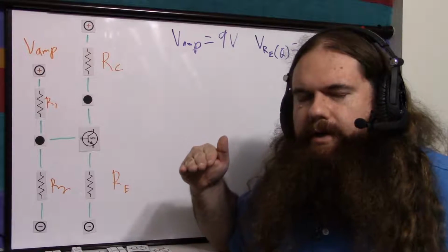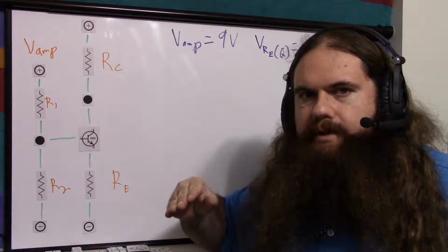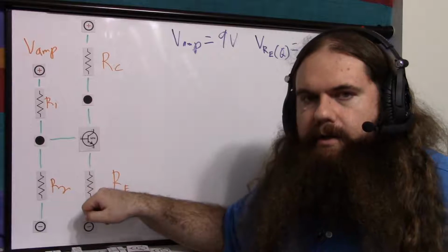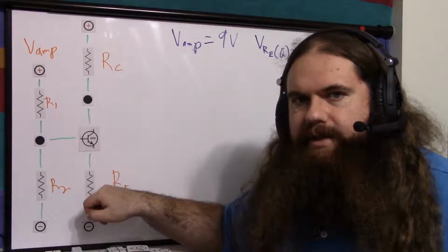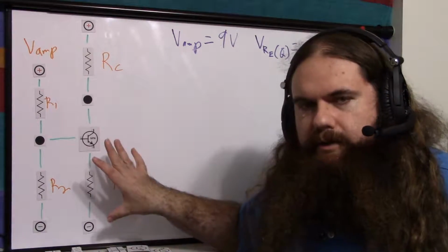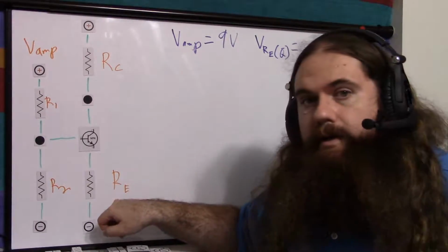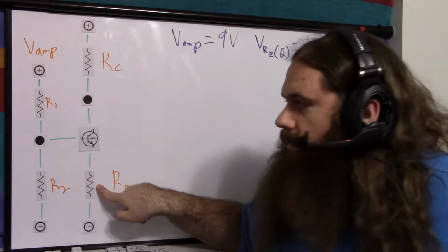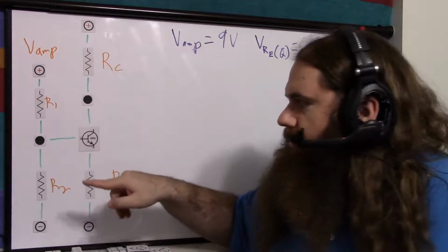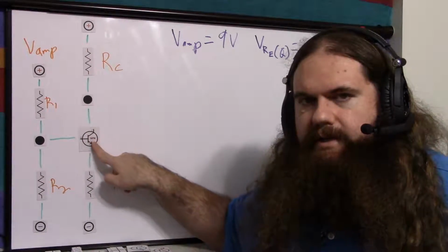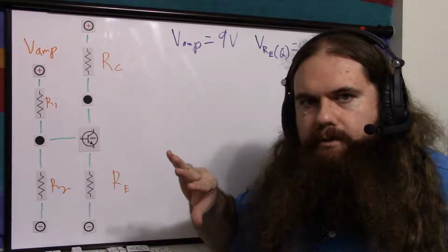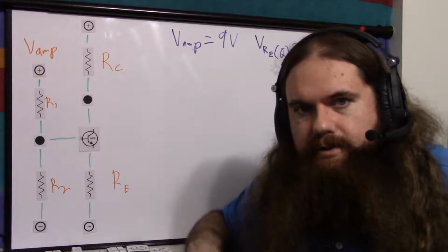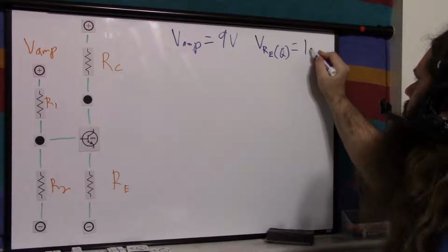Now, you're probably not going to have a signal that goes all the way to minus 1 volt. So this is probably not going to go to 0 and you're safe. But if you think the signal might be stronger, then increase the voltage drop on RE to make sure that the signal never dips it down to 0, because if this goes to 0, then your signal pushing the bias down is going to start eating into the base to emitter voltage, and you're going to lose that forward bias and your transistor is going to turn off. But right now we'll just say 1 volt.